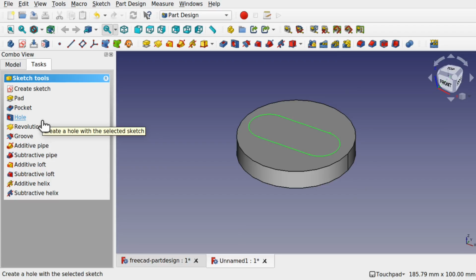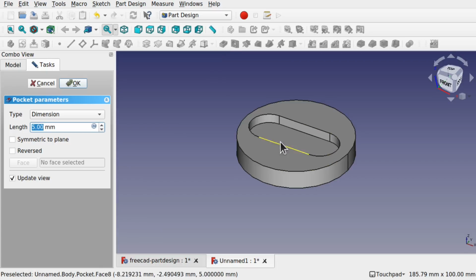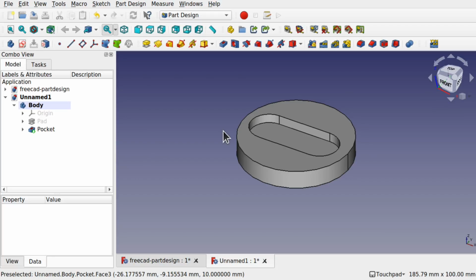So if we look at the Part Design compared to the Part, what's happening is we're going to be in a contained workflow in the Part Design, which allows us to create our models without breaking out to other workbenches. We'll break out to the Sketcher, but that's really the only one that we're going to be using in there. There are other workflows that interact with the Part Design, but not many. But I'm just going to add a subtractive action to this, or subtractive feature, and hit OK.